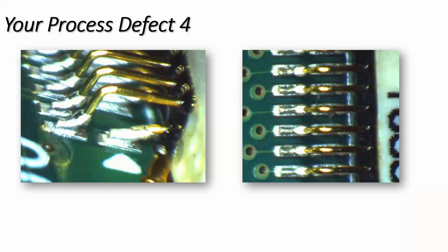Next thing, if you've got gold-plated pins, I imagine they're a very thin gold, less than a micron over nickel or another barrier layer, they'll be very solderable, very wettable. So solder does tend to migrate. Solder does tend to wet these surfaces and pull away. So what we've got to try and do is figure out what we can do to A, get the joint to make it acceptable, B, make it reliable. So whatever we can do in our process. So there's a few things that we can do.